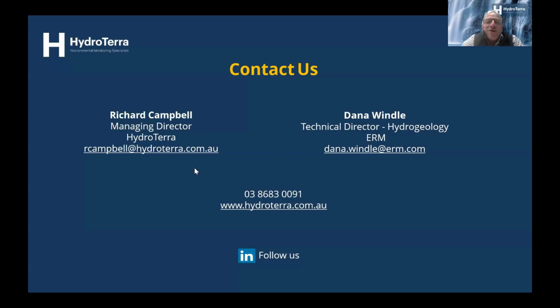Alison Reynolds, for tidal sites, what recording interval do you suggest for the loggers? I generally say start with 15-minute intervals and see what the data looks like after the first download, but I'd be curious to hear your thoughts.